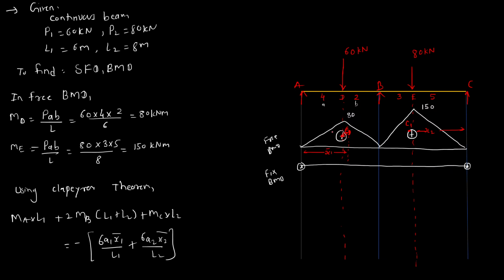So what is the formula here? I am writing it here. For this case, if this is A and B, the distance is L plus A by 3. And the other distance will be L plus B by 3. Remember, this A and B are for this case. If you take the second triangle, and this is the centroid, then this distance is L plus A by 3 and this distance is L plus B by 3. A and B will vary based on the question, so don't get confused here. Take the respective triangle, identify the A and B, and then apply the formula L plus A by 3.